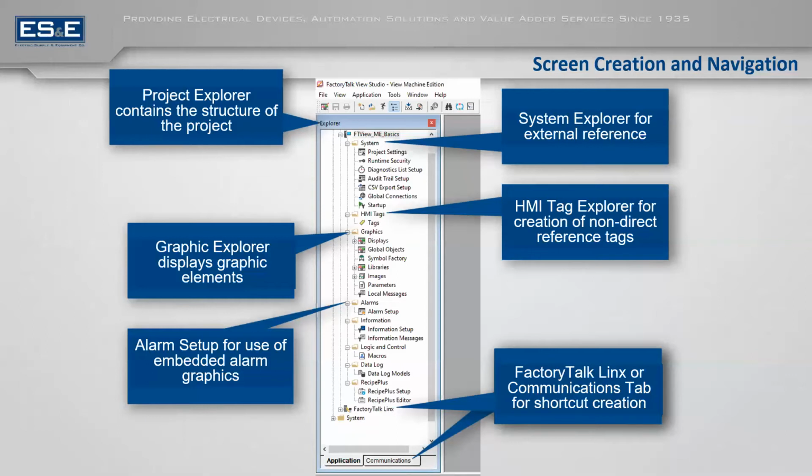The next thing is your alarms setup. So as I discussed in our previous seminar with Studio 5000, the newer platforms allow for tag-based alarming. For FTView Machine Edition, it does not natively grab those alarms. So you would have to set up your alarms still individually.